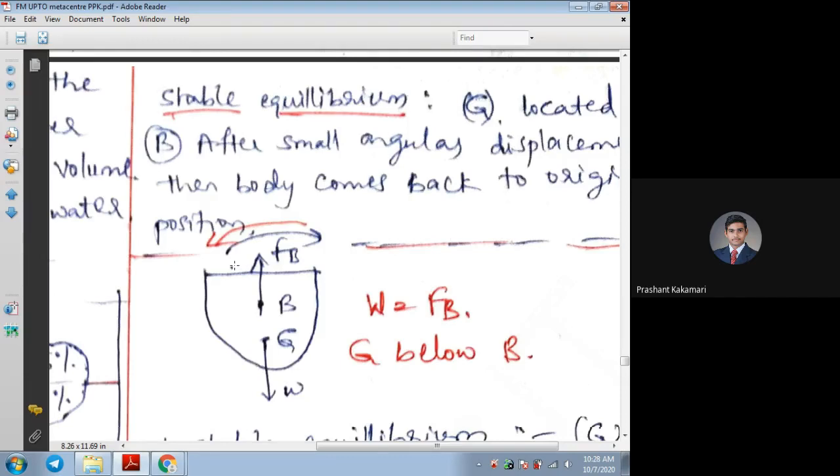In the front view, I can see the movement about this axis in the right and left direction because of the difference in weights, or while stopping and propelling, or even with different loads on the front side and back side of the ship. Again some couple will be generated, or a moment will be generated about the center axis.